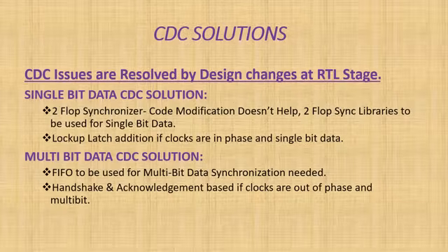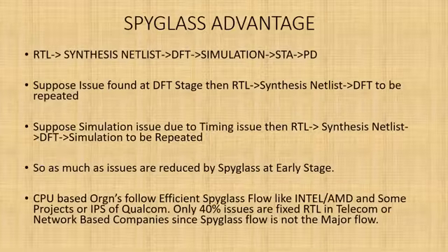Got an idea why we need SPYGLASS CDC early in the stage? Because some of the issues we can only resolve at the RTL level. The advantage is we will reduce the multiple iterations.